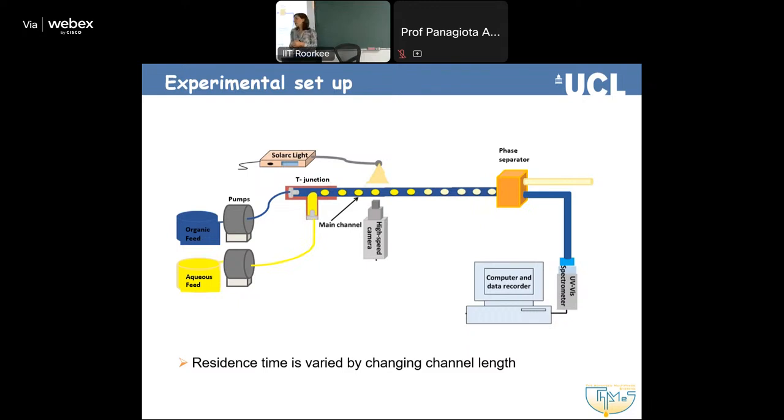Basically, the membrane is based on different wettabilities of materials. The two-phase mixture goes there. One phase likes the membrane and goes through, the other doesn't and stays. So then we can get one phase, usually the organic, and the other phase, the aqueous, that we can pass into UV-Vis instruments. You can have UV-Vis spectrometers that are continuous as well, and we measure the concentrations, and that's how we get the data.